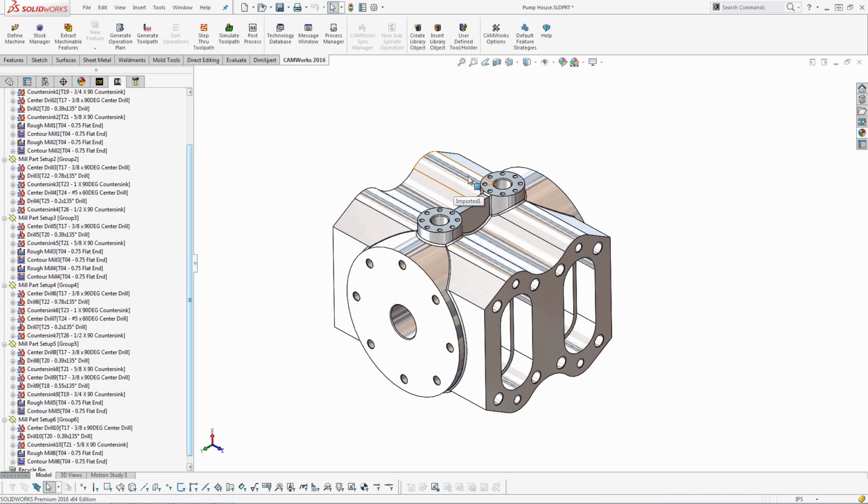A lot of this curvy stuff, assuming it came in as a solid block of billet, we would probably have to do some 3-axis machining. If it came in as a piece of a casting, then I could read that in as my stock shape. We have other YouTube videos on how to do that. So what I want to do now is just talk about the actual indexing.